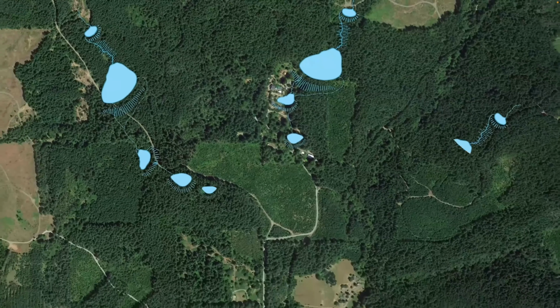In addition to this work of looking at the cross sections of the soil, we also want to evaluate the structure of the soils. And so we can utilize a number of different field tests to look at that. We can carry out an analysis of the different soil profiles. And from each profile, we can collect clay and do a texture by feel analysis. That's one way of determining whether or not there's enough clay to adequately hold water. We can also look at the relative percentage of sand, silt, and clay by taking samples from each of our soil horizons and doing a jar test.